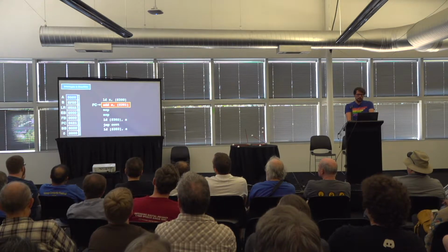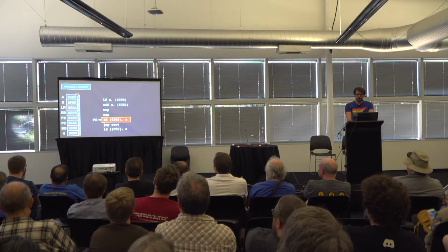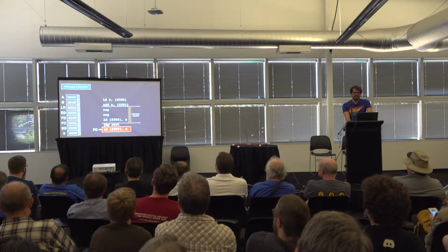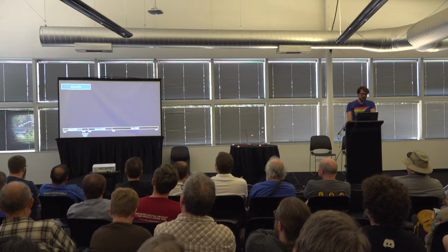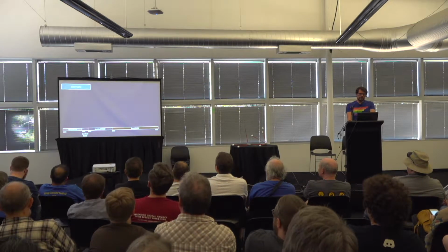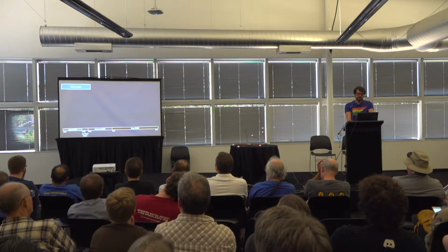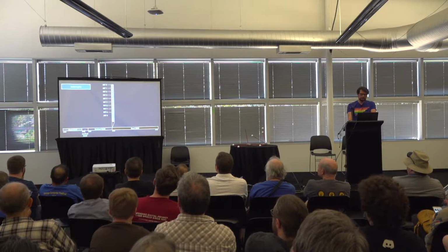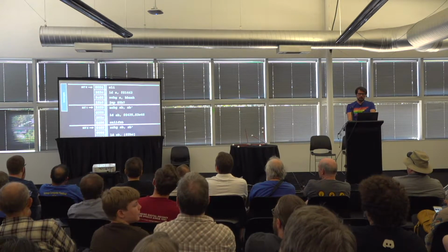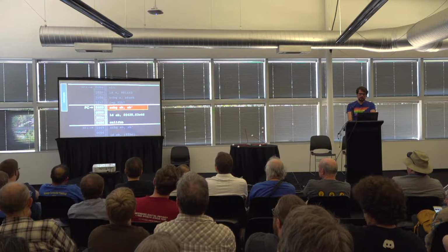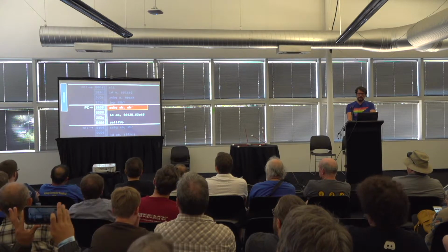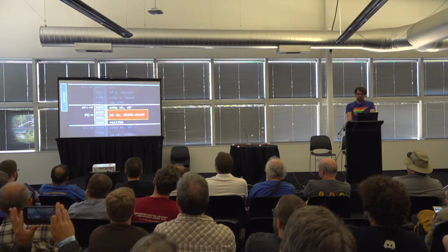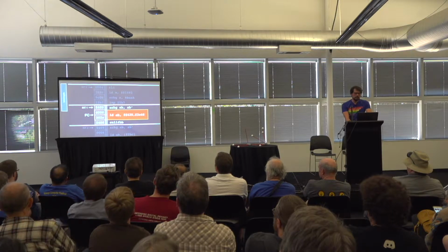So while there's an overflow condition, until the next store instruction, which resolves the overflow, interrupts are automatically disabled. The 11 interrupt handlers have to reside at the start of fixed ROM at 800. There are 4 words for each entry. Typical interrupt entry code saves A and B, loads A and B with a bank and PC of the actual handler, and jumps there.